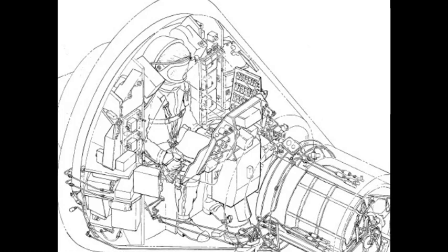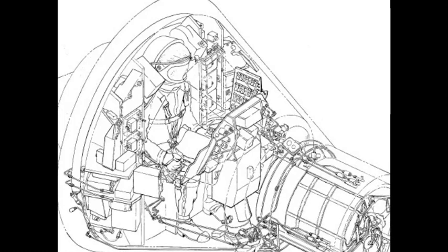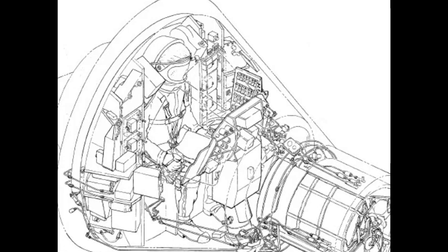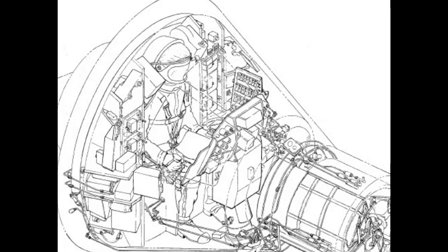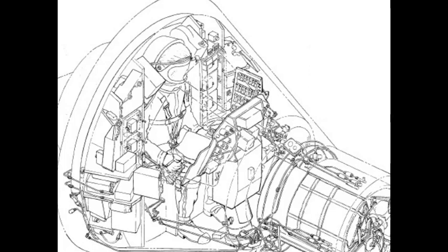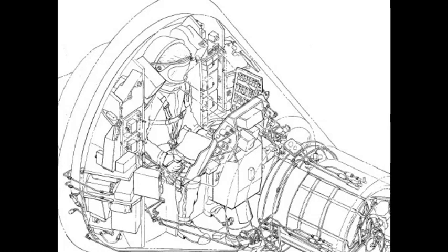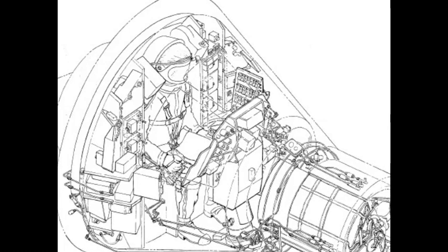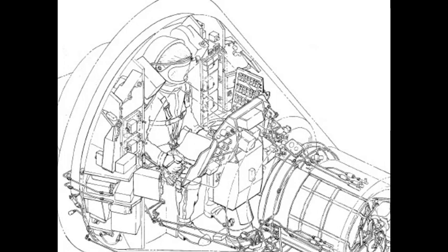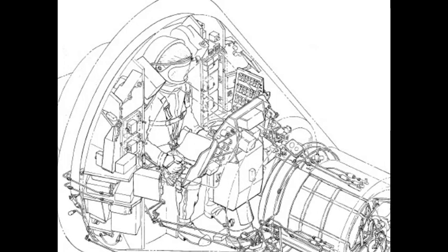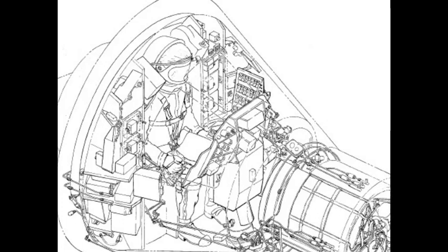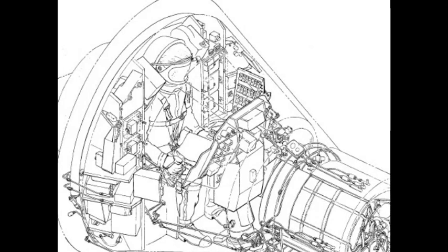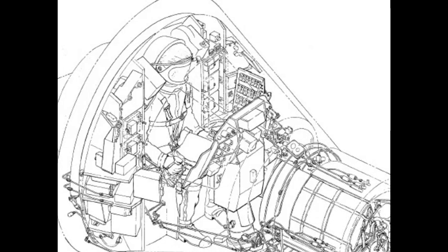The hatch shingles are attached to the hatch stringers, but in no manner are they attached to capsule shingles. This enables the hatch to separate cleanly upon ignition of hatch explosive charge. Following capsule impact on land, the astronaut actuates the hatch release control, which in turn explodes the hatch from the capsule. A hatch release control is also provided on capsule exterior to enable ground crewmen to explode hatch in the event the astronaut is unable to explode hatch.